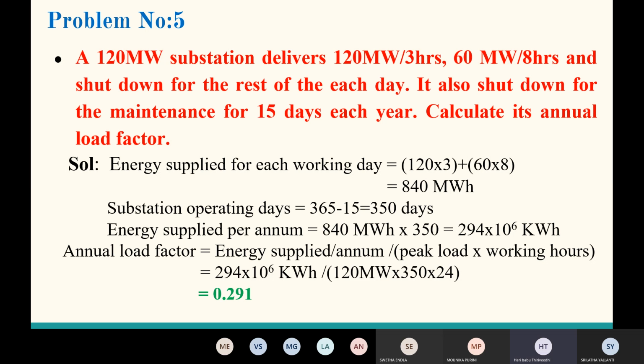Now annual load factor equals energy supplied per annum divided by peak load into annual operating hours or annual working hours.